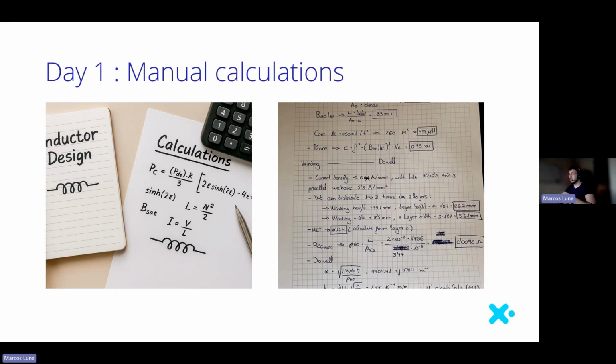You have an amount of losses, or a resistance called AC resistance, that produces extra losses. So we not only need to consider the conductive losses, we also need to consider these AC losses that are produced by the skin effect and the proximity effect.